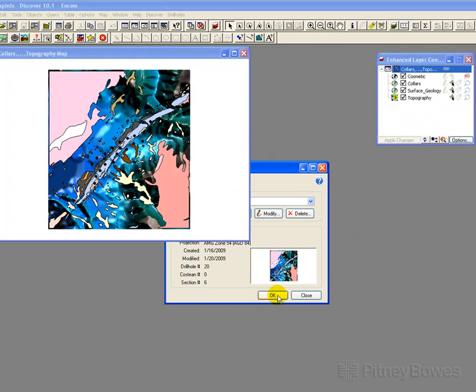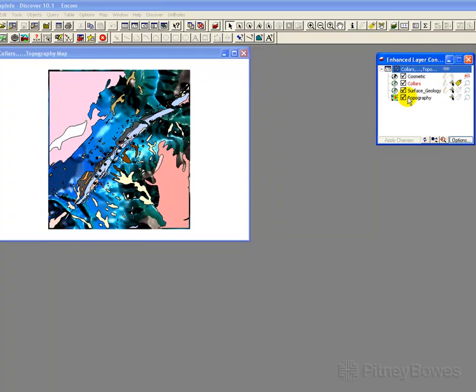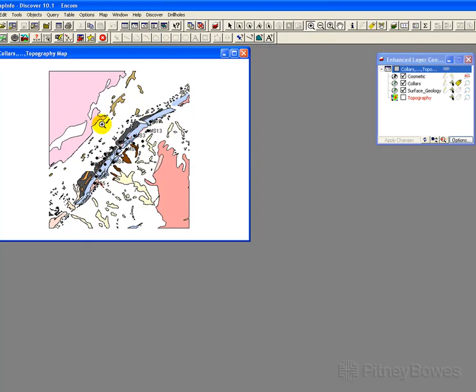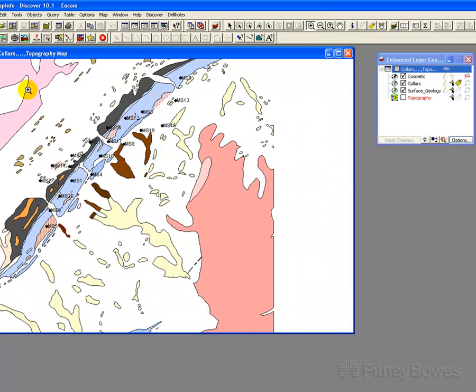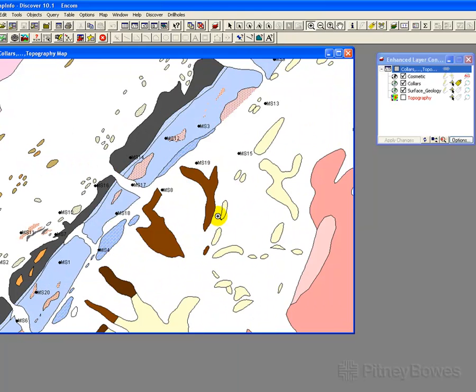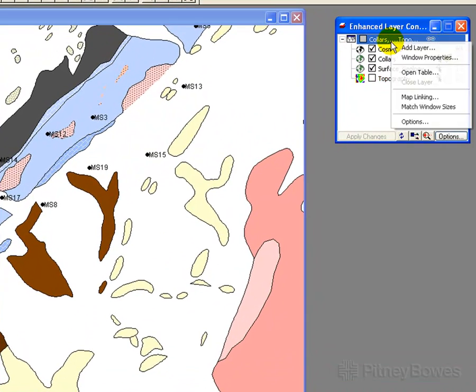There are a number of methods available to define the spatial location of your cross-section. We will examine using a selected line to control the cross-section's extents. This can be either drawn freehand in the cosmetic layer, or a better alternative is to select a line from an existing table of drill traverse lines. This second option is recommended as it also facilitates easy regeneration of existing cross-sections, for example after infill drilling or RC tails have been conducted.